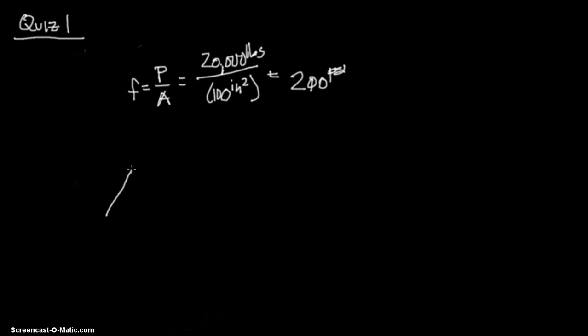So this is the elastic region, and then if you continue stressing it, sometimes it's like this, where this is the yield point, and this is the ultimate stress. And you want to keep it in here because it starts getting longer and longer, and it will fail your structure because it's too long. But it won't be a sudden collapse where people die. It'll hopefully start to bend and people will notice and nobody will get on it.